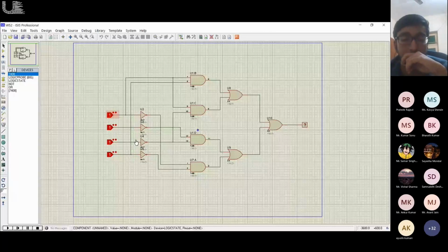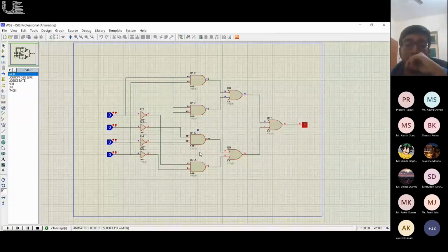And the same circuit, whatever was the result that you got, which is AD plus B bar D plus B bar C bar plus A bar D bar. If you notice, I have 4 AND gates for all of them, NOT gates for inverting each of them, and then 2 OR gates to sum it up, and another OR gate to sum up the result of that. So if I play it, then for 0 the answer is 1. Basically, I can abstract this entire part inside a single circuit. If my input to the circuit is 4 zeros, ABCD is 0, then my output is 1.